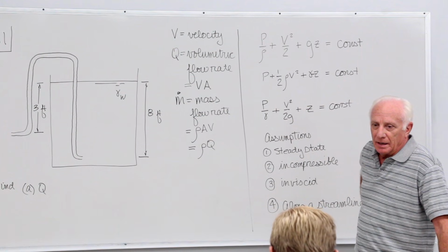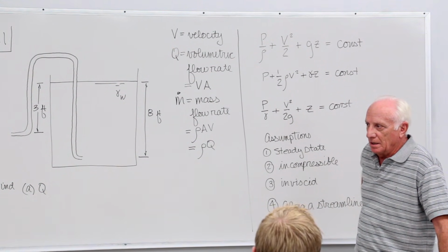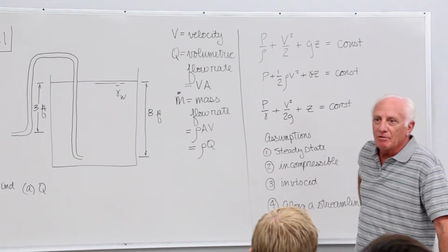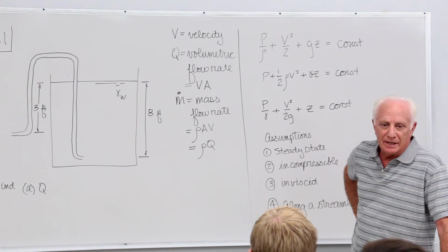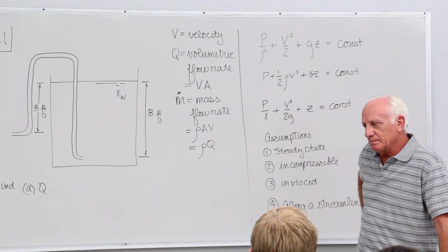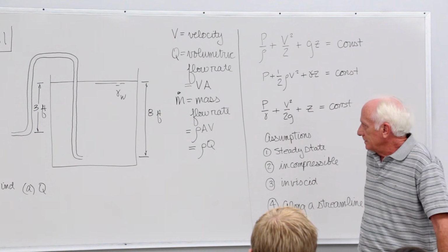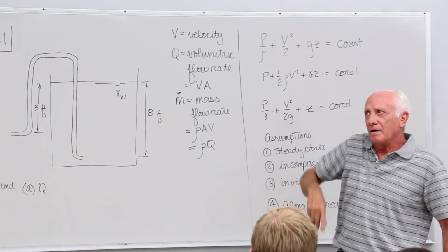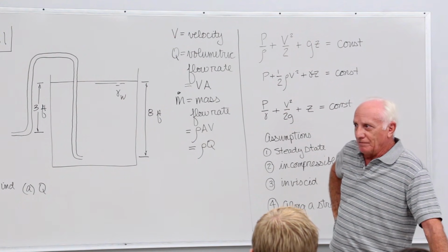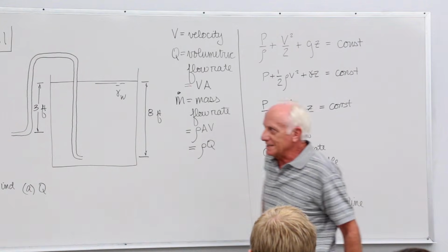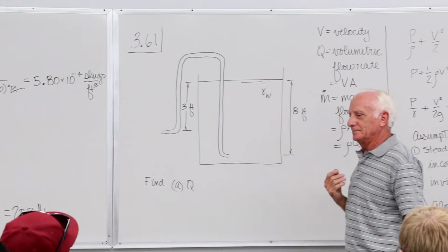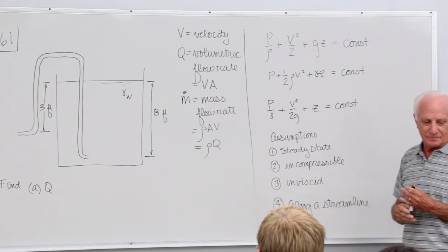An oil pipeline carries so many pounds per hour. In a steam power plant, the line going to the turbine carries so many pounds per hour of steam. They don't say it carries so many CFM. They don't give you the velocity, they give you the mass flow rate in these power plants or chemical plants. If it's HVAC work, they give you the volumetric flow rate, Q. And once in a while, if you're analyzing flow in a river or something, you might want to know the velocity. You want to find V. So there are various times you want to find each of these 3 things. It depends on who you work for and what your job is.